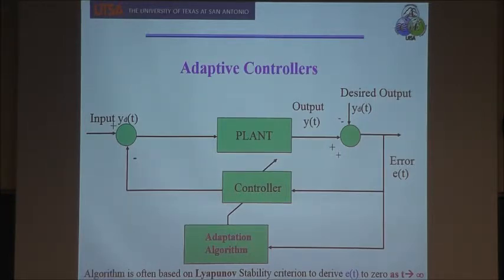If the model has 200 variables and you're hanging on to 25 of those, something has to let go of 175 modes of that system which are not represented in your model. You follow me? Therefore, in real application of that controller for that plant, some of those 175 modes may be excited and there is no way to compensate for it because it was not part of the control design process. Okay? In the space industry, they call it a spillover problem. It spills over to something which cannot be handled.